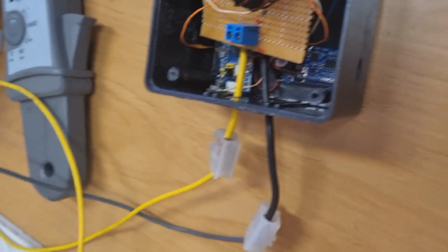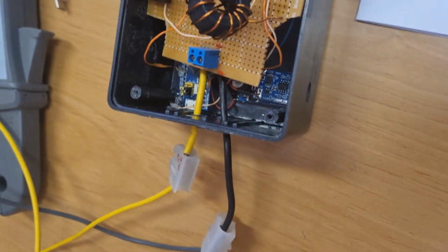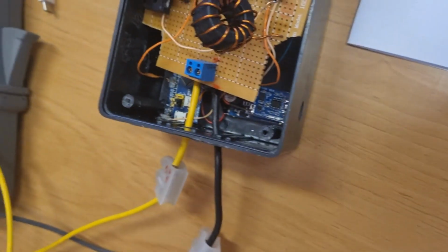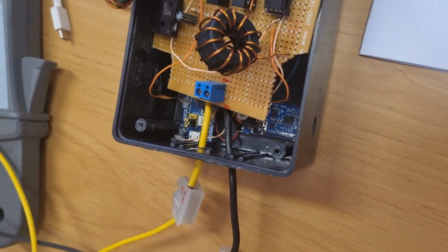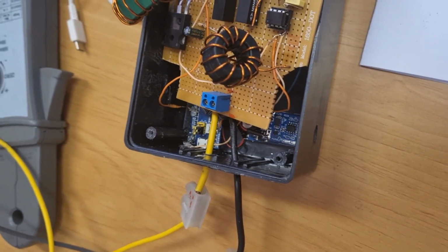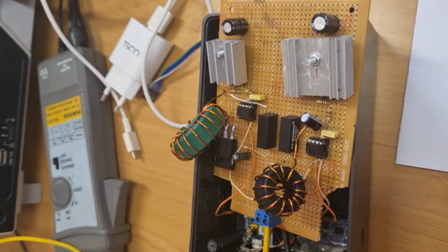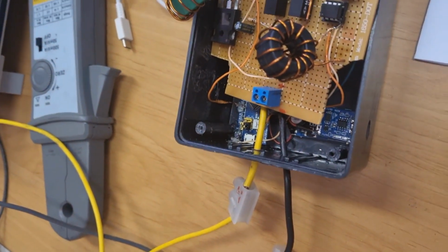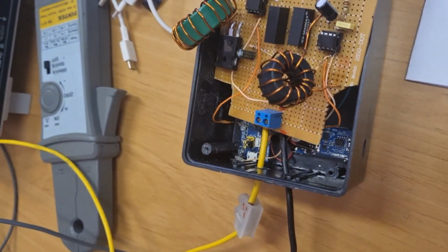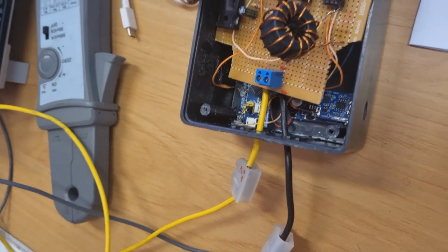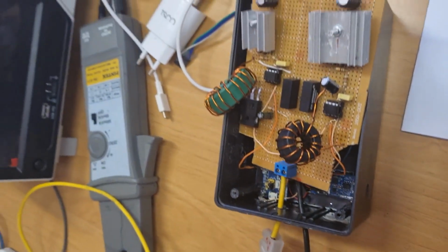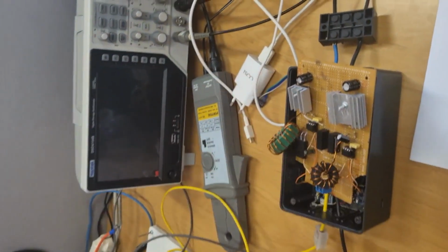And about this microcontroller, I programmed this STM32F1, and I used timer 1, which can provide output pulses, and it gives complementary signals for us. So I used timer 1 channel 1, and I did all this project by myself.